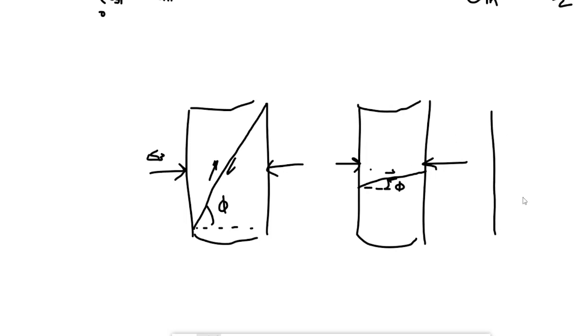And then, of course, with anything, we could take it to the extreme and say, well, what if we had a completely horizontal shear plane? Now you have stresses coming in like this. Is that really going to strengthen it at all? No, those stresses are just going to transfer along that plane perfectly.